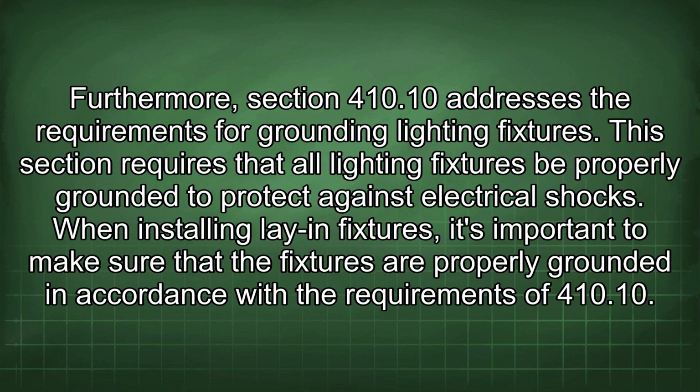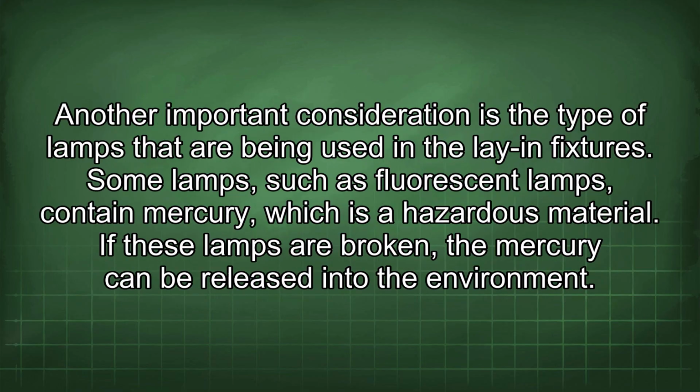Furthermore, Section 410.10 addresses the requirements for grounding lighting fixtures. This section requires that all lighting fixtures be properly grounded to protect against electrical shocks. When installing lay-in fixtures, it's important to make sure that the fixtures are properly grounded in accordance with the requirements of 410.10.